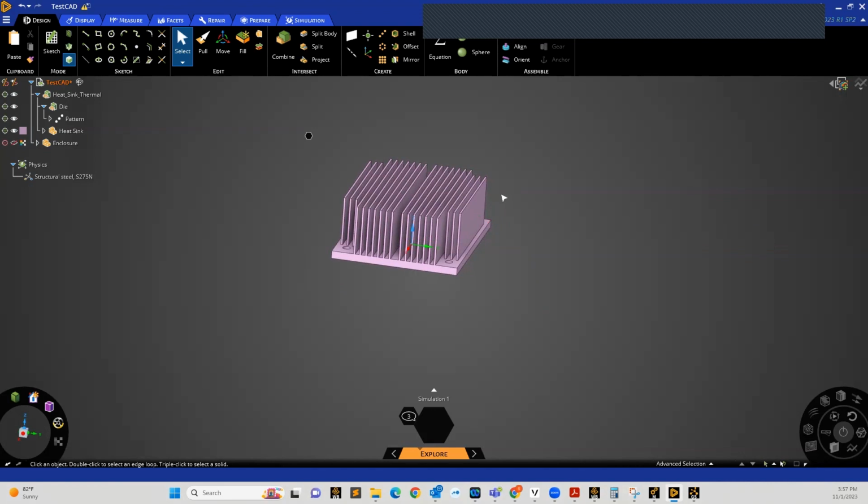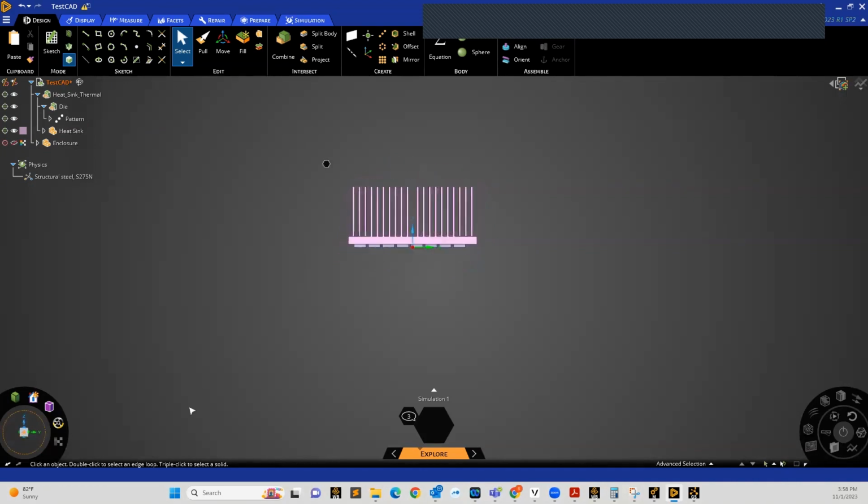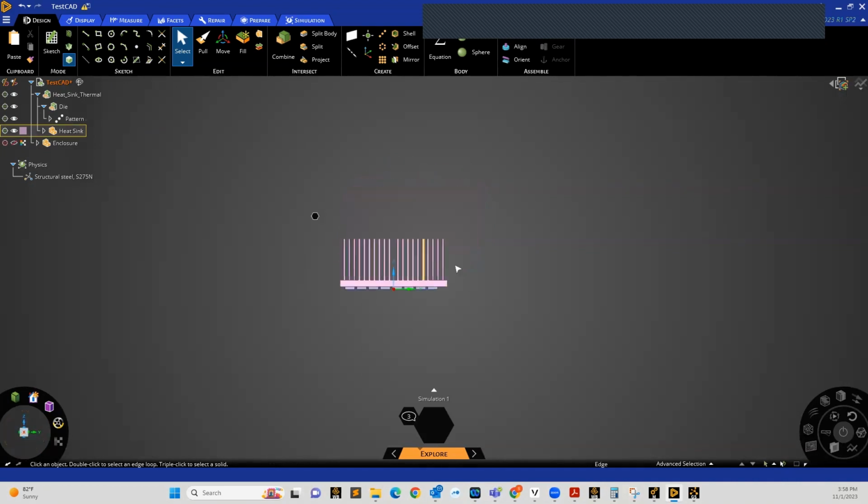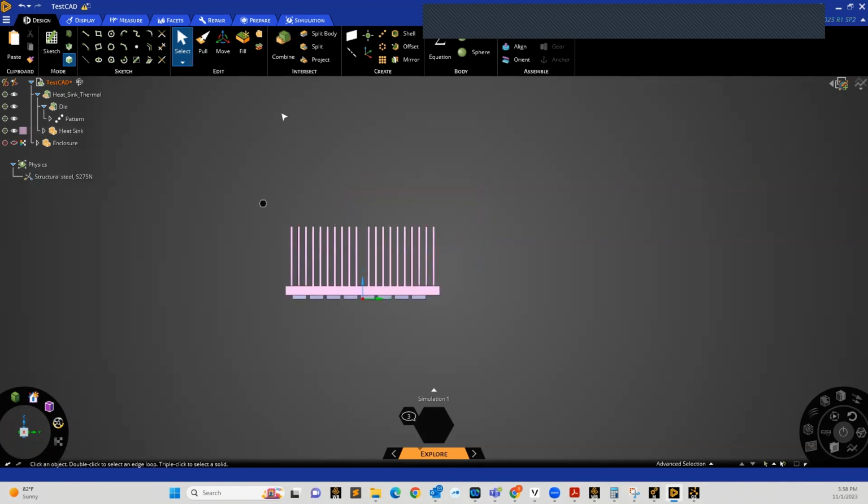So to do that, we would need to create a parameter such that we can manually change the height of those fins, right? Otherwise, we would have to manually come back and adjust each individual model, right? So in Workbench, we would have to come back, change the height, run a model, and then change it again and run it again, and so on and so forth. We don't want to do that. It's going to be too time consuming. And so that's what we use parameters for, to help us automate that process. And the way that works is we can use these different tools from within the design tab of Discovery here to help facilitate that.